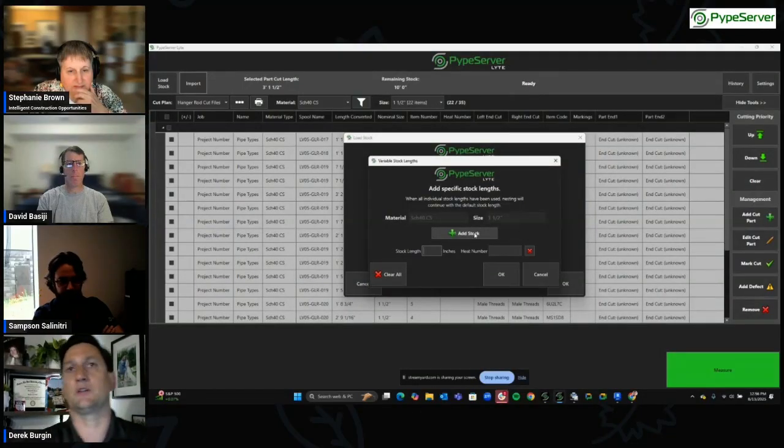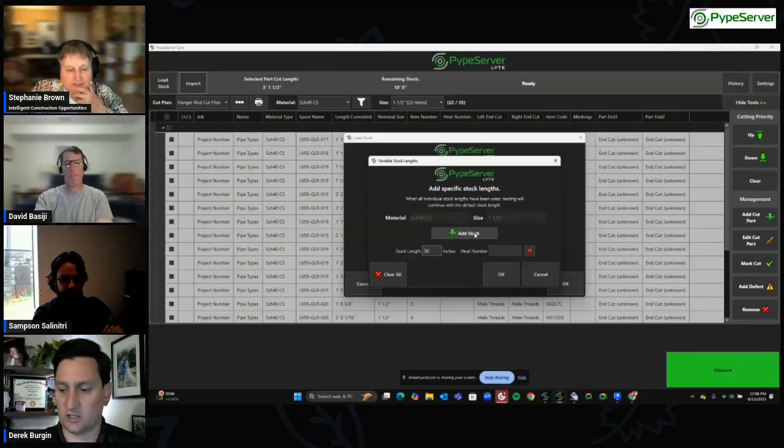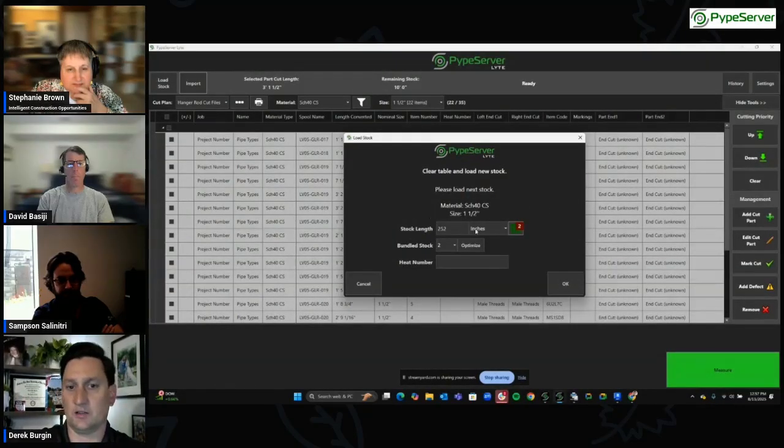But say, for instance, our shop has a scrap pile. Those scrap piles can be ever growing, but let's put them to work here. What we have the ability to do is say, hey, we have a piece that's 36.5 inches. And if you're doing heat number tracking, we can go ahead and throw that number in right there. Then we could say, hey, we have another piece that's 96 inches and it has this heat number to it. And then after that, it's going to go to our standard stock length of 252.